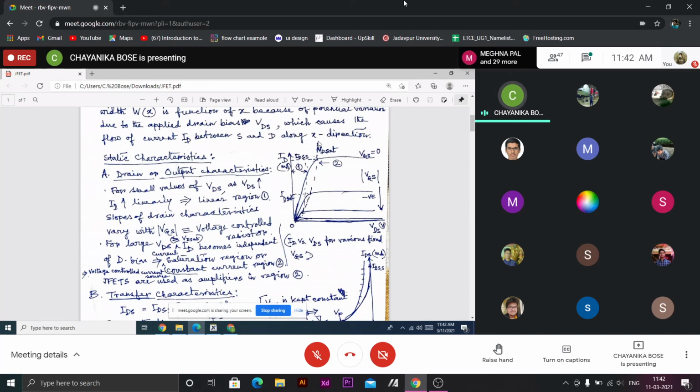And also the drain voltage VD saturation at which pinch off takes place, where the device enters the saturation region, is less, because the effective reverse bias is the difference between the negative voltage applied at the gate terminal and the positive potential the channel gets due to the drain voltage, and that difference is the pinch off voltage.